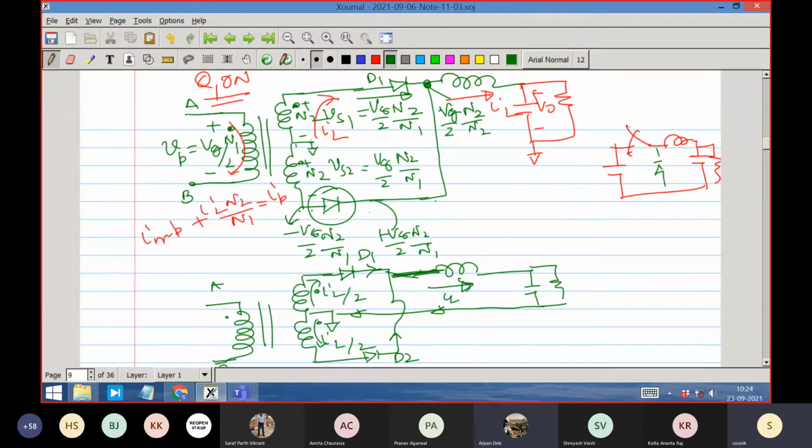So in this state, if both the diodes conduct, then if we apply KVL, the total voltage across the secondary will be 0, right? Yes. That's the point. If you do the KVL, you will see that this secondary voltage has to be 0.